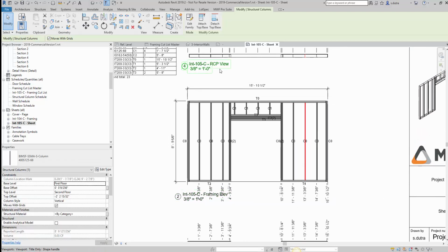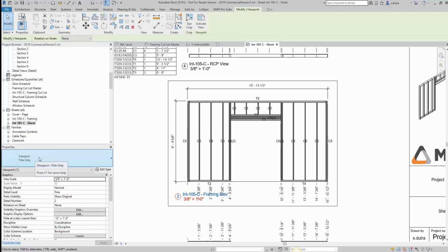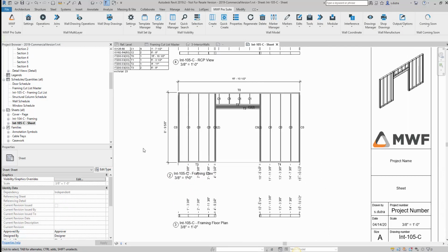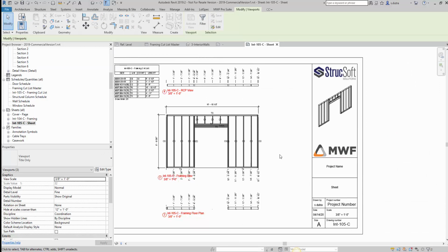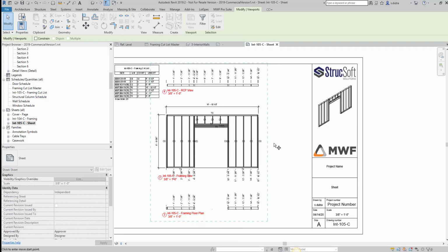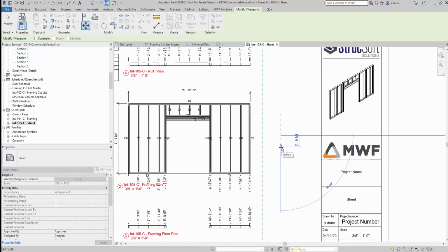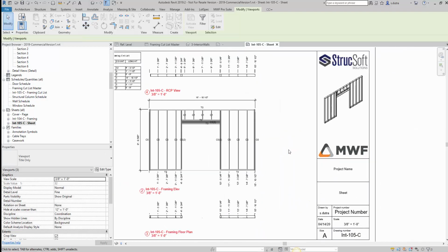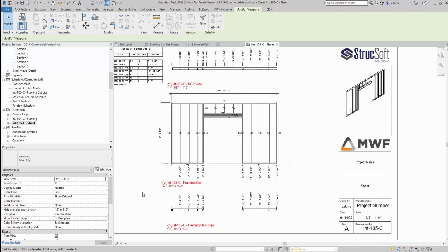So this is actually a Revit family. What we used when we did our viewport was to have the view title only. If you have the line, this might not work, but if you're just using this method, it might work. First thing we're going to do is measure out how much we need to move it. So let's grab all three of them here, just make sure that they all fit into that sheet. Let's move and let's just measure. Let's see, half an inch. Half an inch seems to be fine. So let's go ahead and move that half an inch.